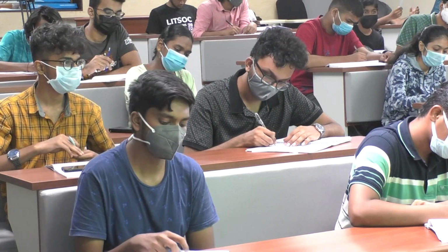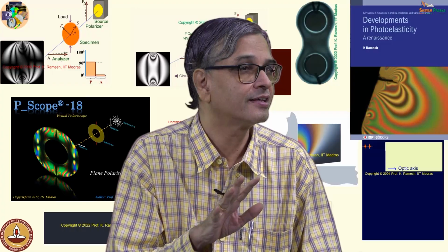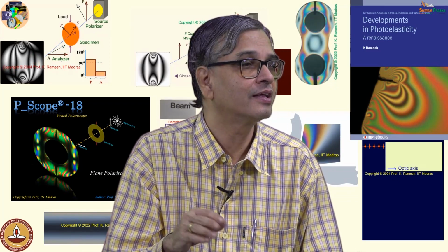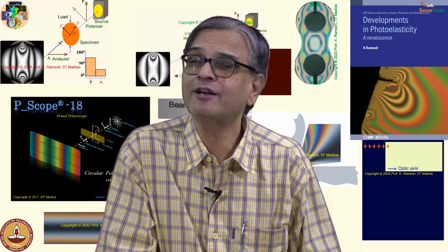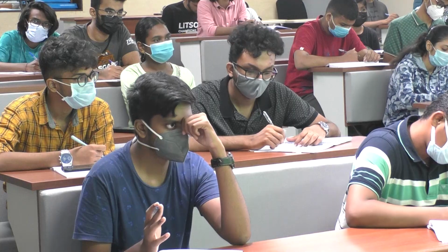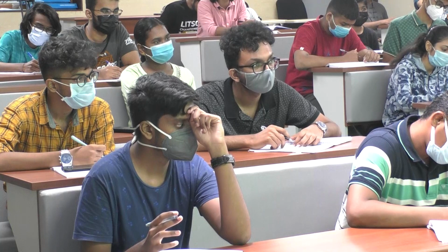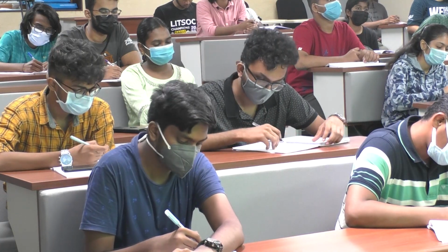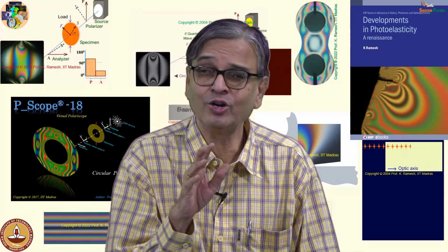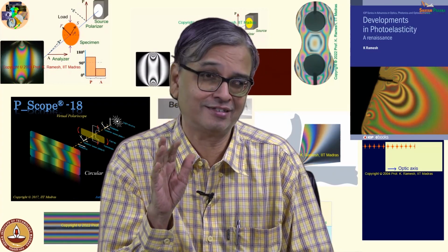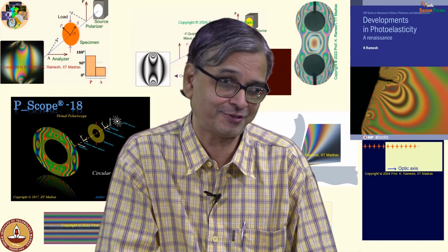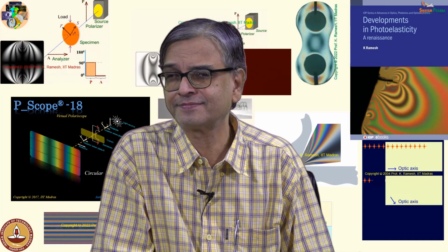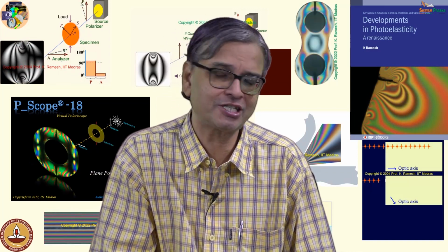See, I am living in linear elasticity, okay, and I am reducing the load by half. What do you anticipate to the principal stress direction? Stress magnitudes are changing. Stress magnitudes are 1/2 of it. You look at the expression. See, there is advantage why we want to live in the linear region. You should also taste that advantage. What do you anticipate to the principal stress directions? What will happen to the principal stress direction?